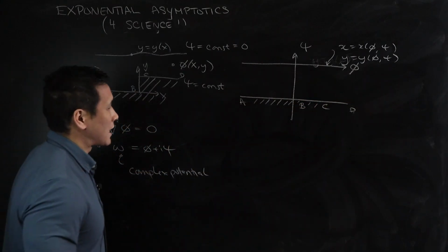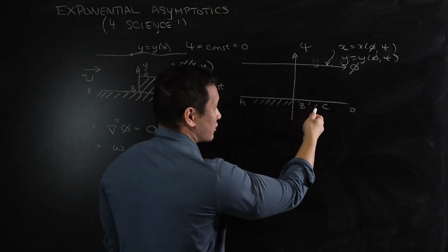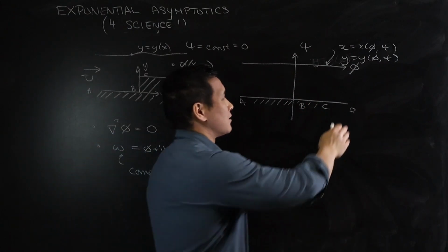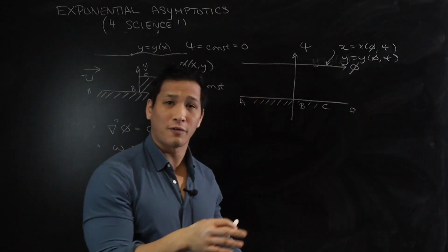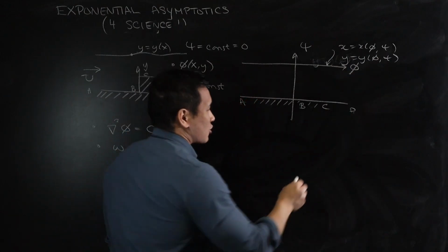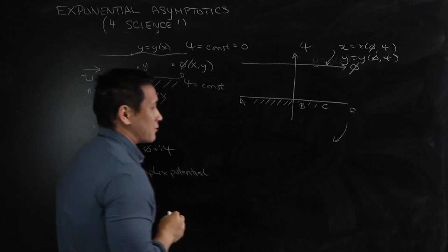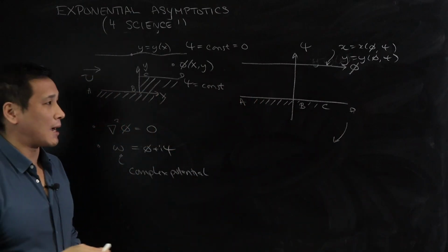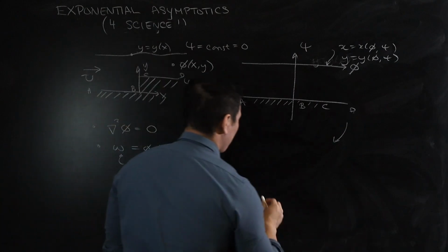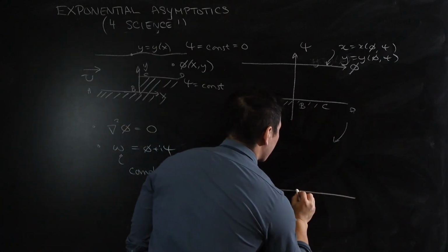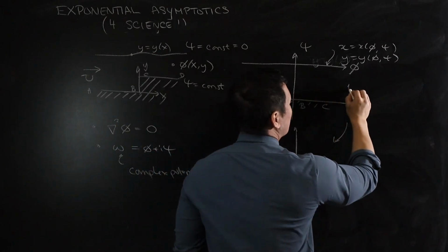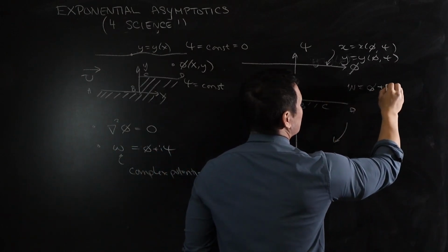Okay, and so now the next step, once you understand that you want to write down your set of equations in this inverse formulation way, where phi is now an independent variable, it turns out that for our version of the problem, it's convenient for us to remap this domain into the upper half plane. So I want to perform a coordinate transformation to send me from this W plane. Remember, W is phi plus i psi.